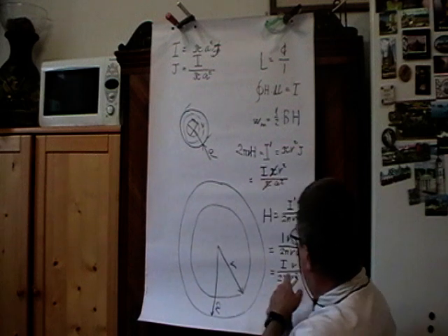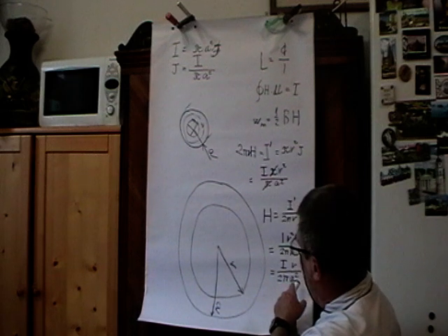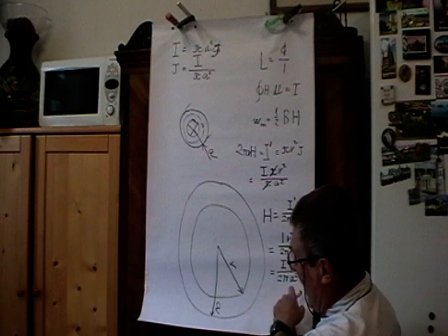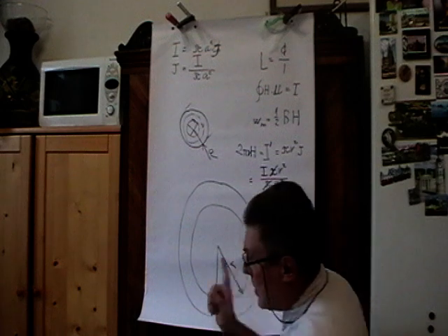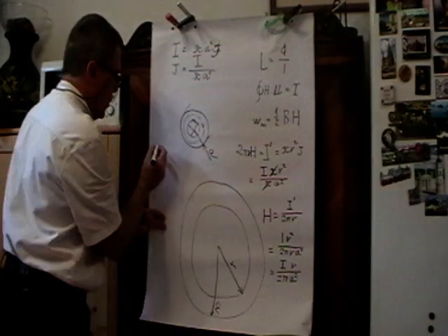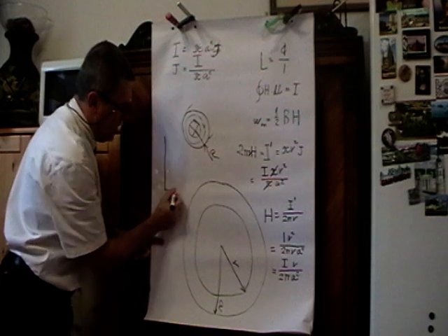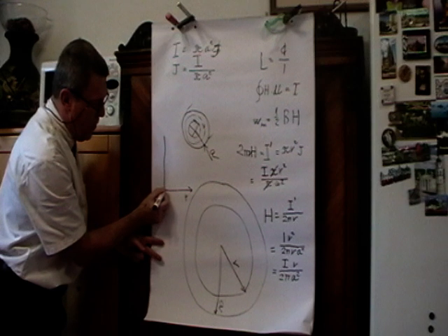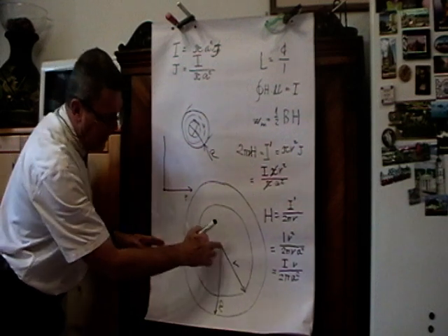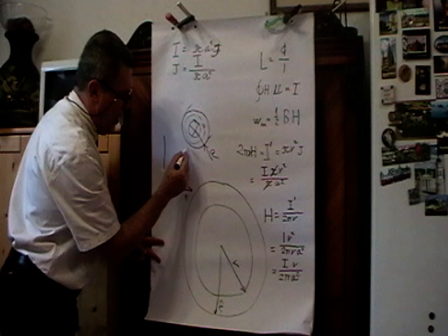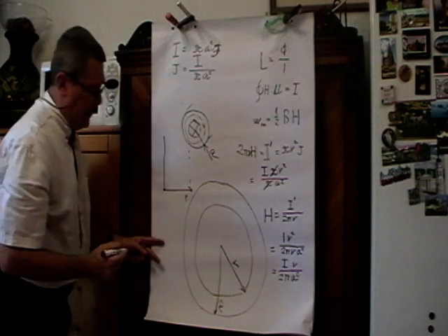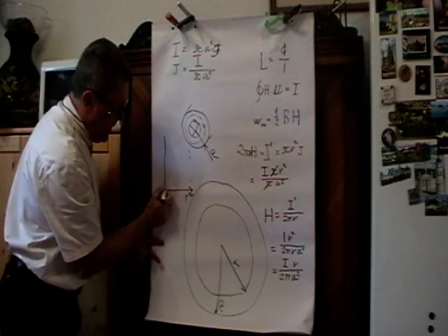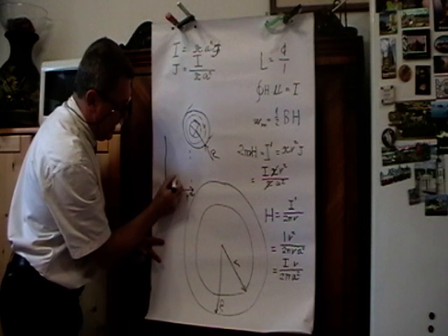So now we have established the behavior of the flux or magnetic strength inside the core. I will just illustrate it on a short graph. If we have the radius, so we have zero magnetic field at the center, then up to the distance called A, up to the radius of the conductor, there is a straight line.